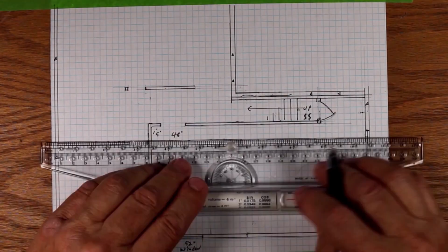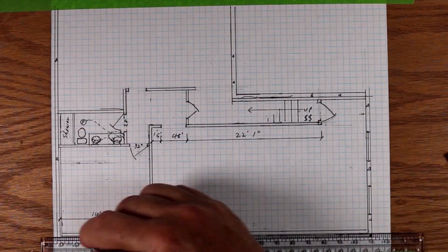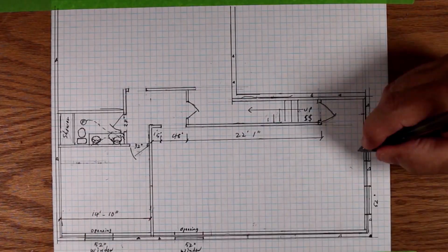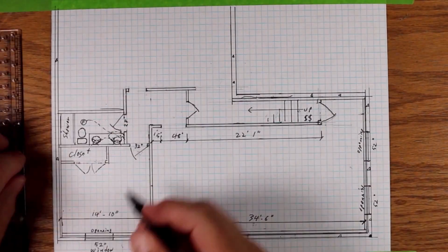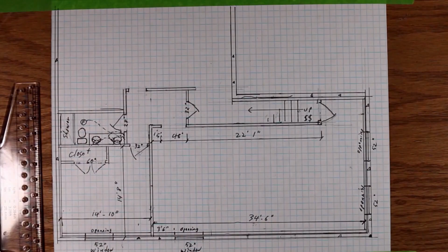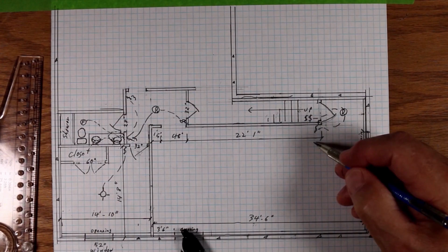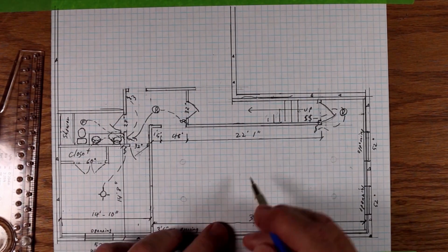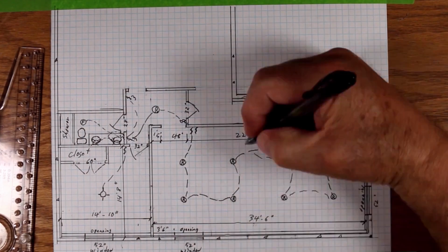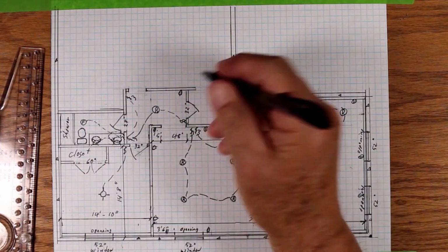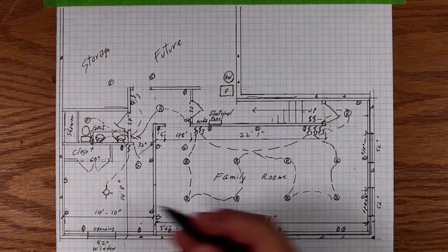Don't worry, just get close. Once you get what you have drawing completed, then do all of the what I want stuff. Label your rooms, door sizes, window sizes, electrical, lighting, cabinets, plumbing, toilets, showers, sinks. Don't forget dimensions. Write down all of your dimensions so that others can read your drawing. From this drawing, you can calculate the cost of your project.